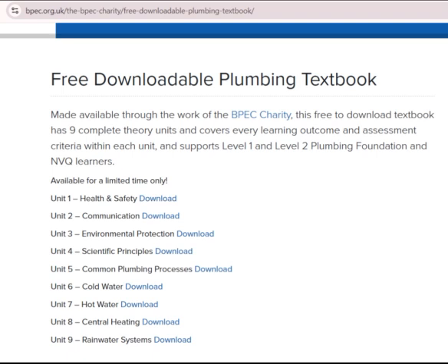AC 2.1 Identify the working principles of central heating systems. AC 2.2 Identify the type of central heating system from layout diagrams. Traditionally the most popular form of heating system in the UK, wet central heating systems rely on the circulation of heated water around a circuit of pipework to heat some form of heat emitter or, in the case of underfloor heating, the floors of the structure of the building itself.